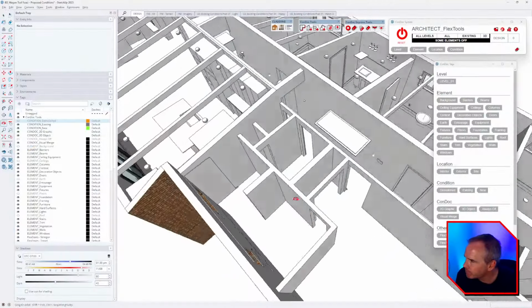And if you think about it too, when you need to create your drawings, you only need that one model. So in order to create your demolition plan, we're going to be able to isolate the demolished entities on their own viewport and set it to dashed. And if you wanted to make an existing conditions plan, that would be your existing plus your demolished equals existing conditions. So it's pretty handy to have all this information in this one file.